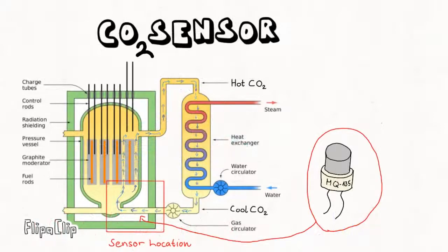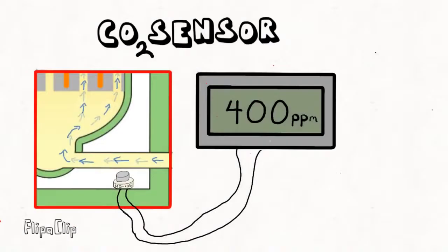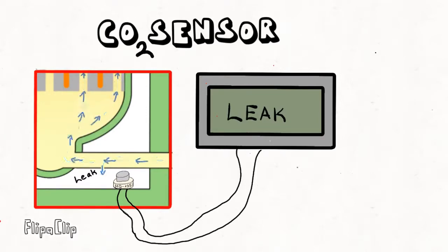The sensor used for leakage detection of the coolant CO2 will be positioned inside the isolated containment building of the nuclear power plant. The CO2 concentration will be measured continuously during the regular operation of the power plant. In case the cooling pipeline inside the containment experiences a leak, the sensor will detect an increase in concentration and send an alert before any further damage can occur.